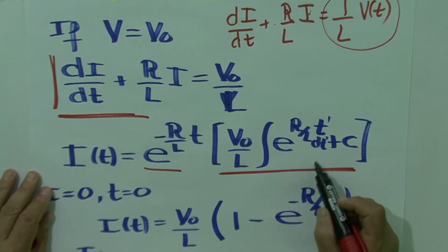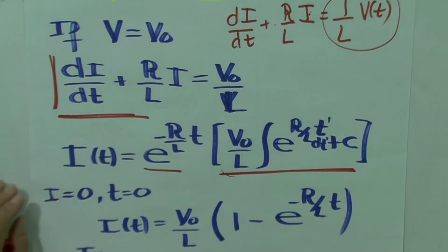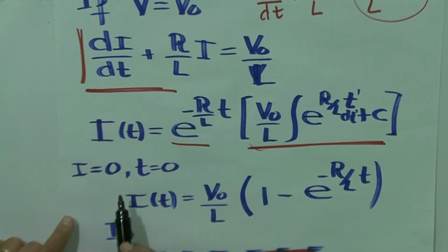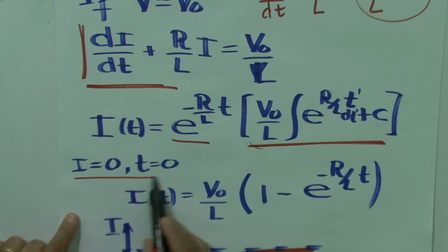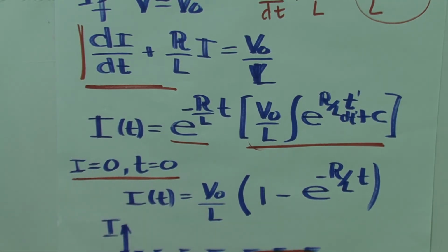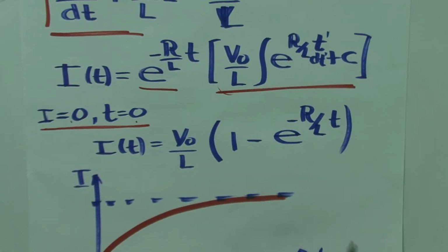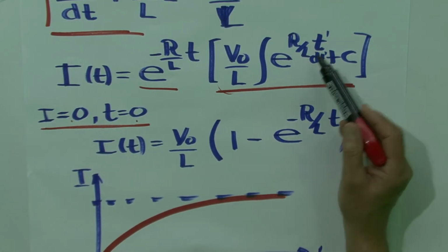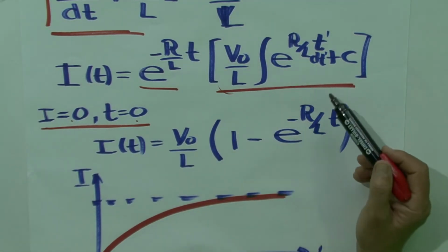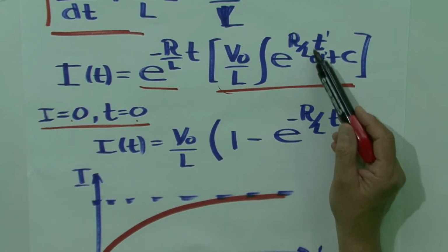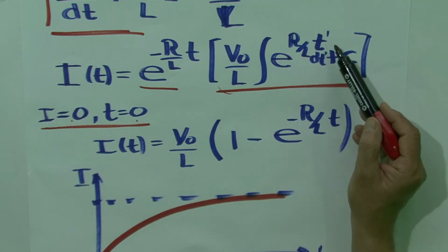We already saw that b is a constant, it comes out. And I have an initial condition: when I connected this circuit, there was no current there. So at t equals 0, the current is 0. Therefore, the integral of the exponential is the exponential. This is a constant, it comes out. And this exponential is nice because it gives you R over L t.